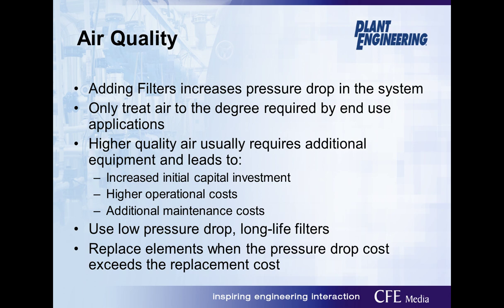So real quickly, for the air quality, obviously anytime you add a filter, it's a pressure drop in the system. Anytime you add any kind of fitting whatsoever, there's a drop with it. So you really want to look at the end use and treat it to only what's required. Because if you over-treat the system, it's going to be more capital investment, higher operational cost, additional maintenance, not to mention the pressure drop, because the more filters you put in, the more drop you have, and the better the quality, the higher the pressure drop is in the filters. So you want to use low pressure drop, long-lasting filters, and then you want to replace those elements when that cost exceeds the cost of replacement.